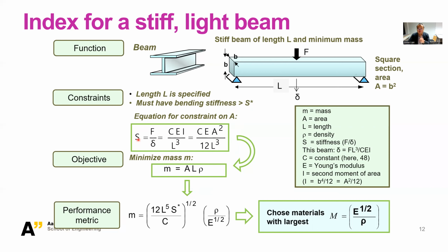Before, we were talking about the tensile strength, which was relatively easy. Now we're talking about bending stiffness, and you need to involve a few more quantities, for example the second moment of area, because this is the way you can express your bending stiffness with the geometry and also with your material parameter, which is the E modulus.